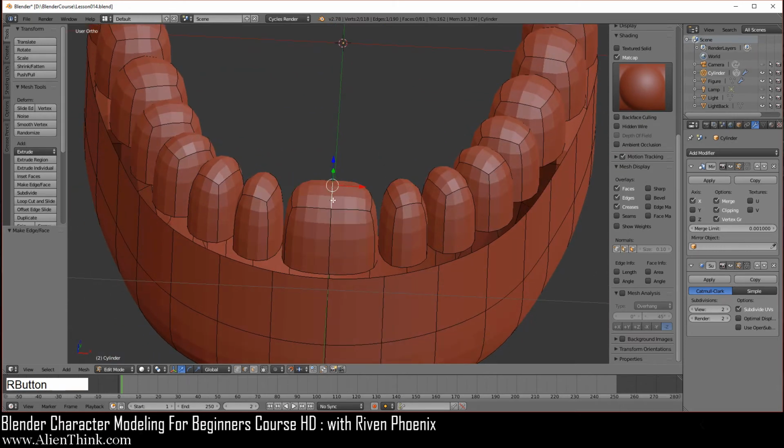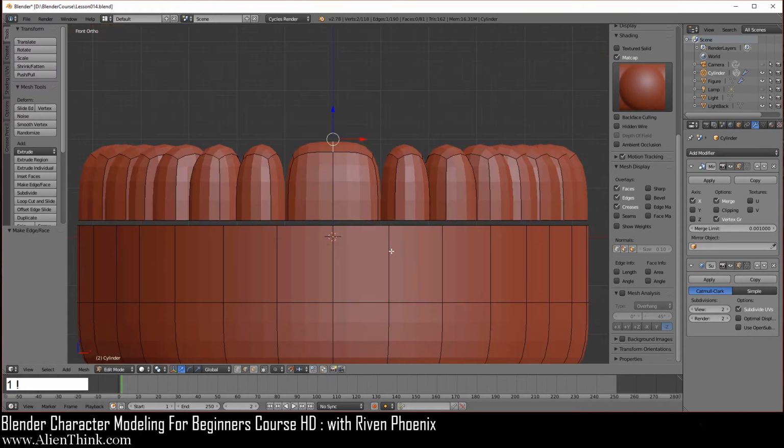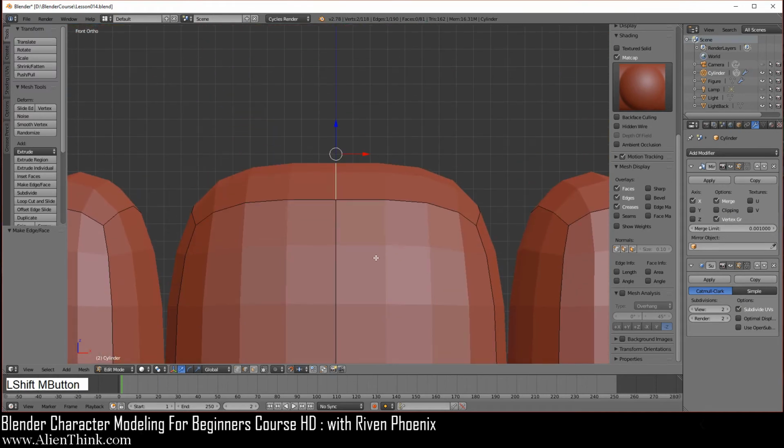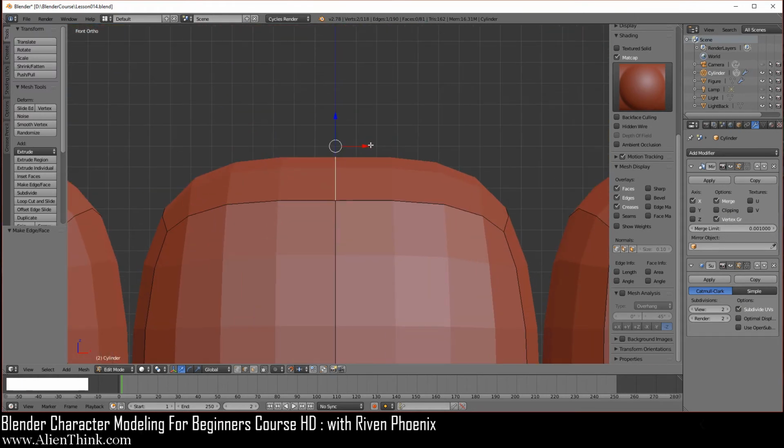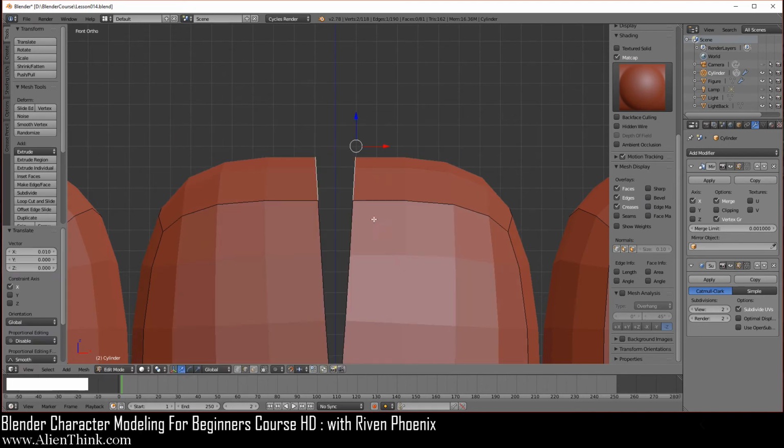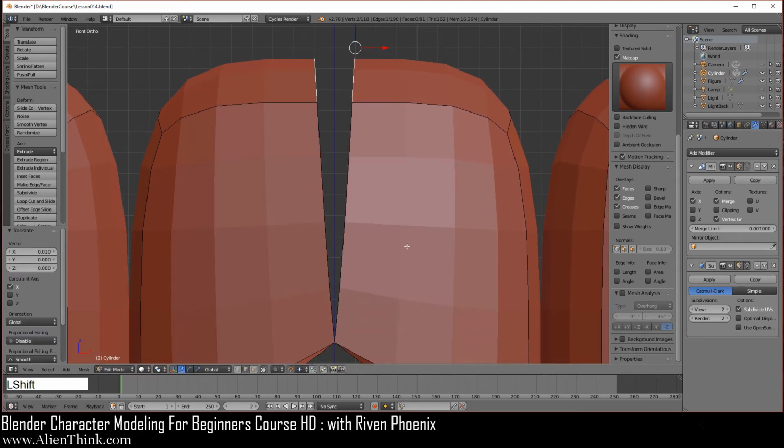Now we can't do the F over here because this is the mirror modifier. It's right smack in the middle. So what we have to do is click this off, go to the front view, you're going to zoom in over here. You got to get this over here. I'm going to take this to the right one time. See how this splits it? You can only do that with clipping off.